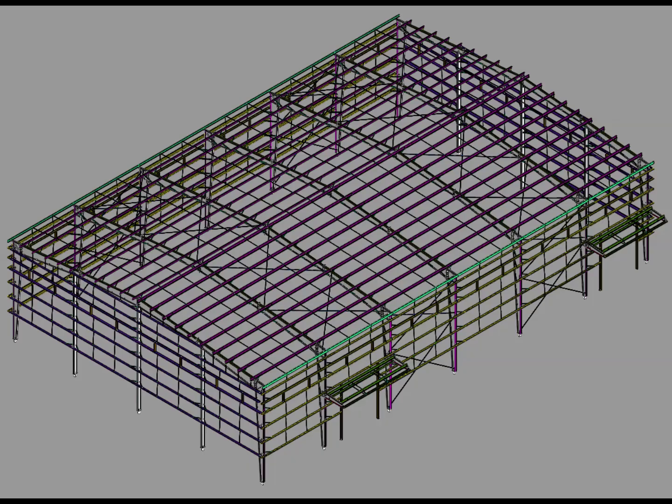It also helps prevent one of the most common mistakes in structural modeling. That mistake is understanding a member correctly in 2D, but placing it incorrectly in 3D. A member can look correct in a plan view but still be located at the wrong elevation or connected to the wrong structural member. That is why the 3D verification step is so important.